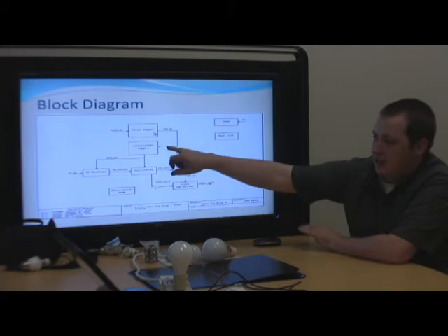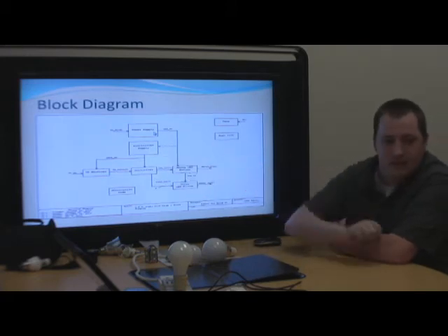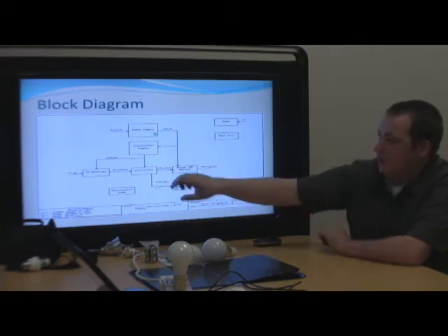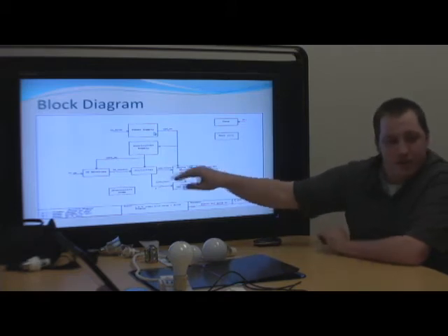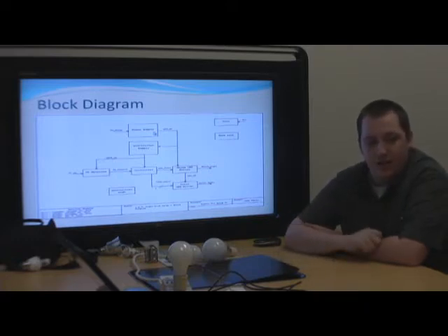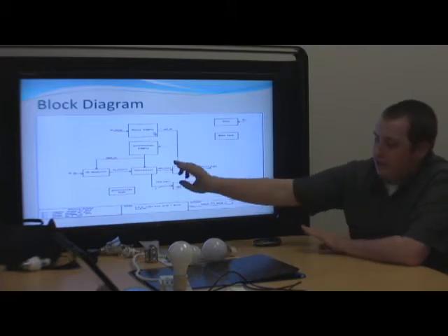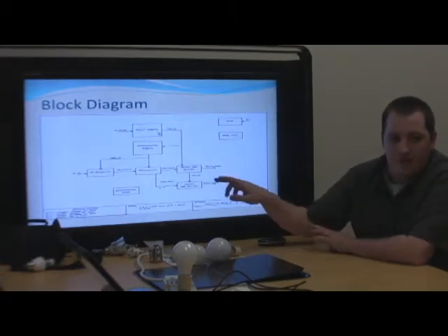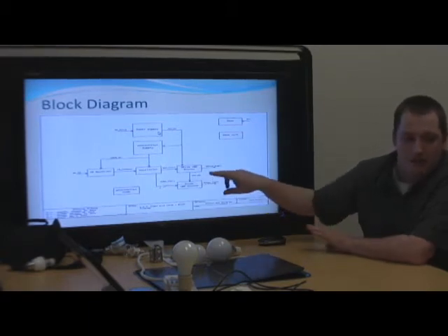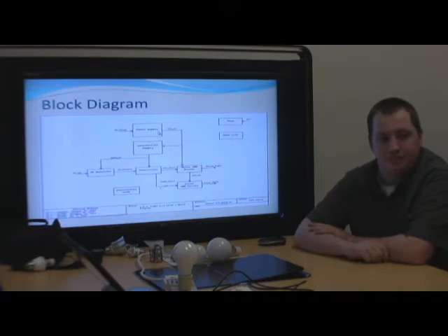This power supply is then used to feed our microcontroller power supply and our LEDs themselves. The controller is used to receive IR signals that determine the color and brightness of the LEDs. The controller then determines a PWM to pulse the drivers themselves, and that's what controls the brightness.